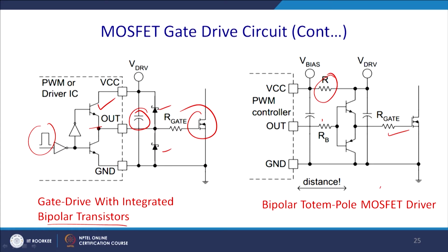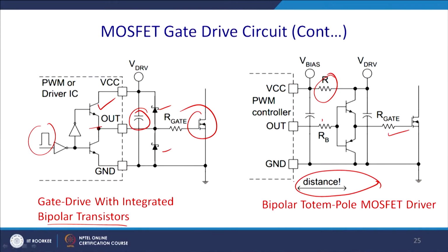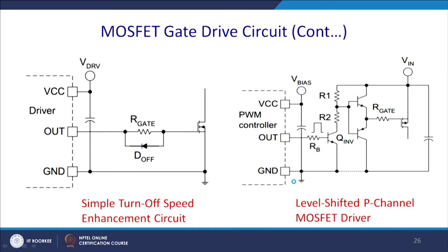And mind it, if the distance is huge, that leads to stray inductance of this gate driver circuit, and that will pose a threat of noise, also in high frequency applications. So, this distance should be as close as possible. For this we have modular units that will reduce the stray inductance of the switches. Discrete components definitely will give rise to stray inductances.